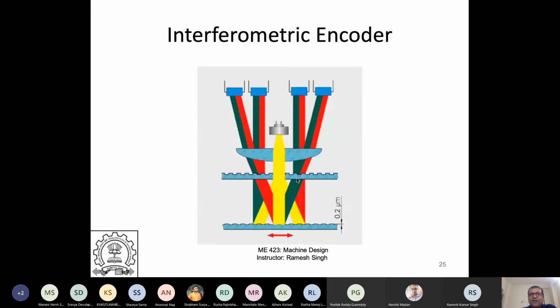You have interferometry, basically meaning that you will have interference between the waves, and you will get alternate light and dark fringes because of interferometry, right? Because the light travels different paths, there will be constructive and destructive interference, and this will create a measure of the distance. So if there is more distance, you will get different fringe patterns. The fringe patterns will give you the displacement. You can actually measure roughnesses of the order of, I would say, they claim to measure sub-angstrom.